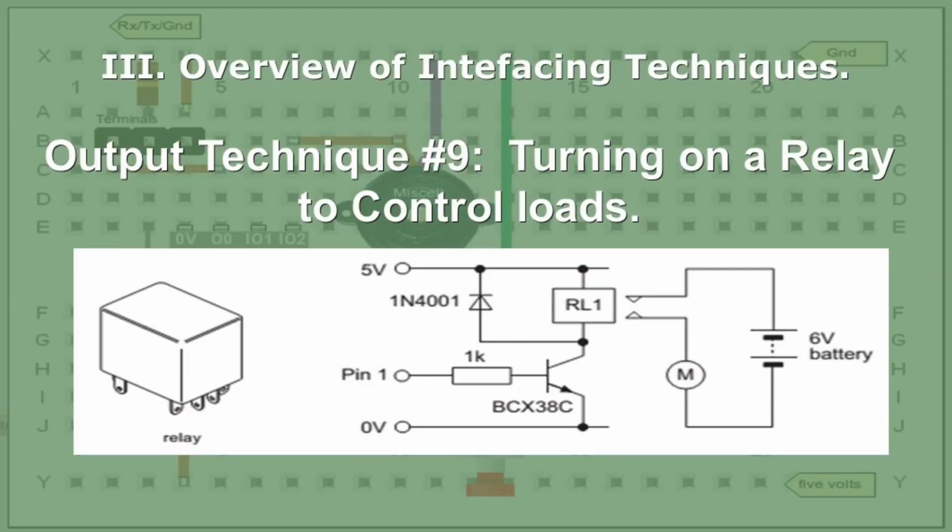Relay. Notice again, the same transistor, the same current limiting resistor there. This is a bipolar transistor, and you're turning on a relay coil. When you turn that transistor on, it provides a current flow through that relay coil, and then the contacts on the relay operate. You can operate a very, very high voltage. This could be controlled with a 220 or 440 volt circuit on the contacts of the relay, but it's only low voltage on the relay coil.